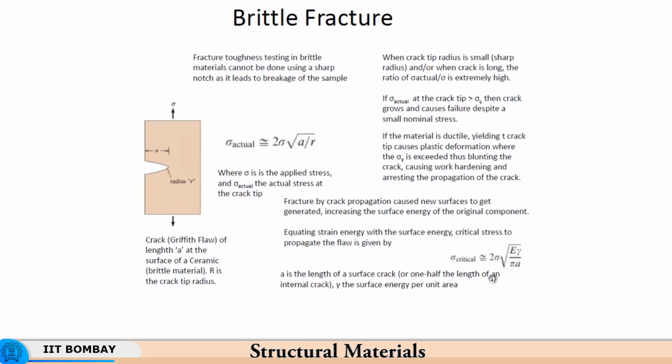Simultaneously, you can also find out, for a given stress, what the critical crack length is. You know that a component is to be loaded, a certain stress is going to be generated in the component, and you would like to specify the maximum flaw size that can be tolerated without any fracture. So, you allow the designer to work with a material with a certain size of flaw, so that even if the material is subjected to the rated load, the crack will not propagate. This is a very important thing.